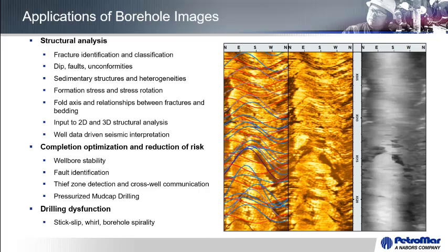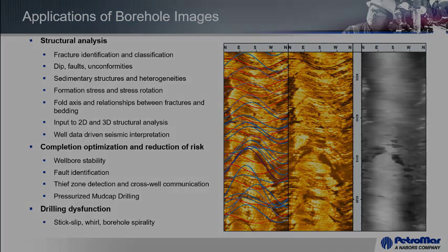In terms of drilling dysfunction, we'll be looking at things like stick slip, whirl, borehole spirality, and how these things interact with the geology as well. Can we see reasons there for some of the effects that we actually see?